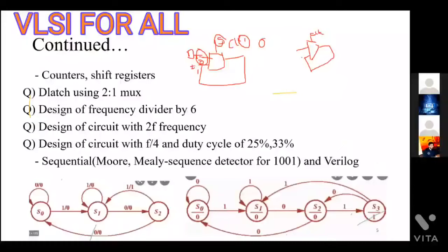If you invert these two inputs, it leads to the formation of a positive latch as well as a negative latch. Now, to generate a flip-flop, you can use a similar concept. The flip-flop is a combination of a negative latch plus a positive latch.